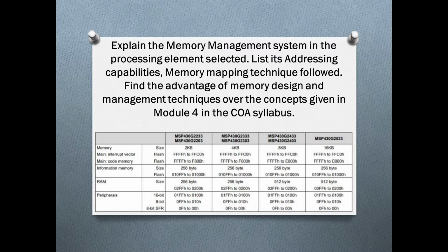In internal ROM organization, various sizes of ROM up to 64K bytes are possible. The common address space is shared with special function registers, peripheral module registers, data and code memory. These special function registers and peripheral modules are mapped into the address range starting from 0 up to 01FF hex. RAM and peripheral organization: the entire RAM can be accessed as byte or word data using the appropriate instruction suffix.